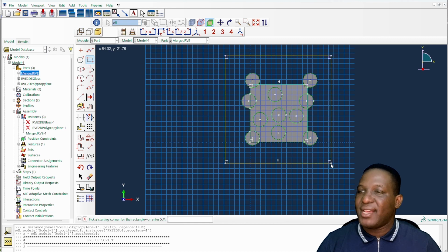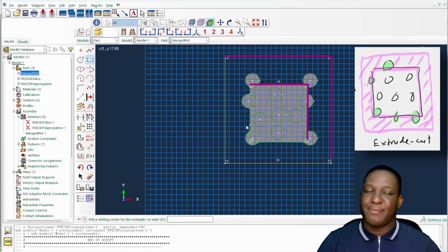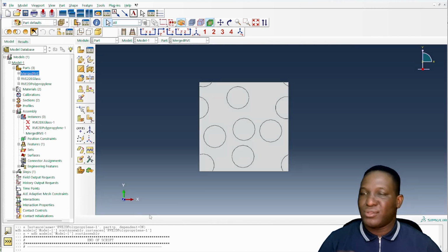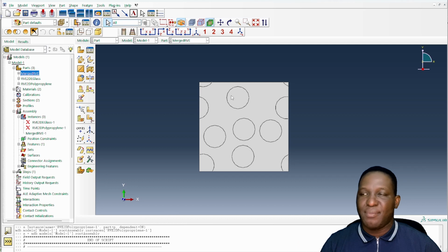And then I'll create a bigger system like I already showed in the sketch. We want to have this system so that the region around here will be the region that represents the extrude cutting option. So after that, then you click done. So that's it. It's extrude cut through the system, and we have a component that looks perfectly exactly where we want it.